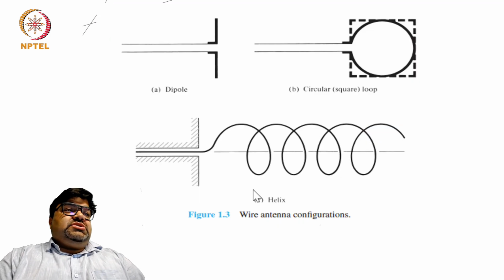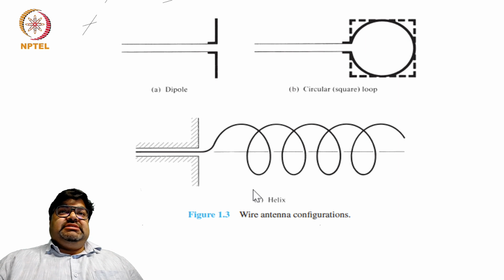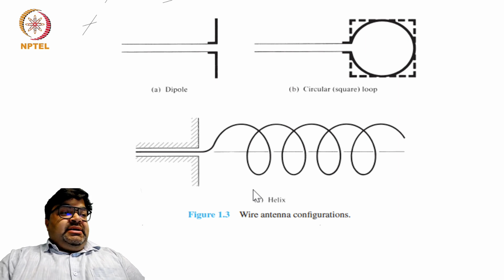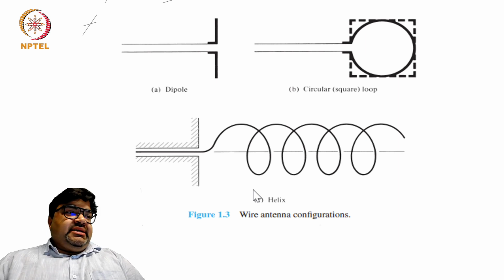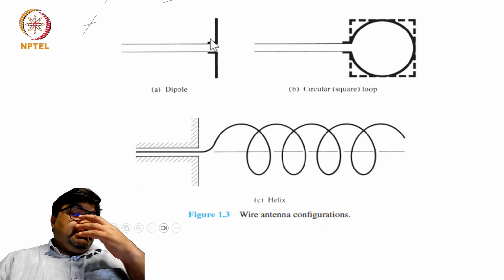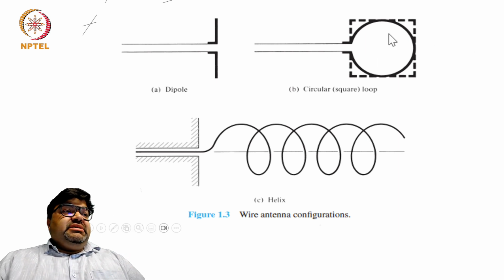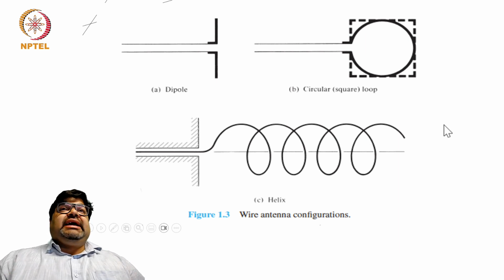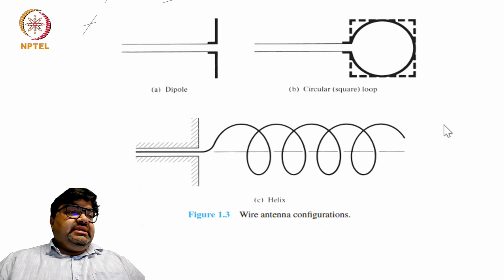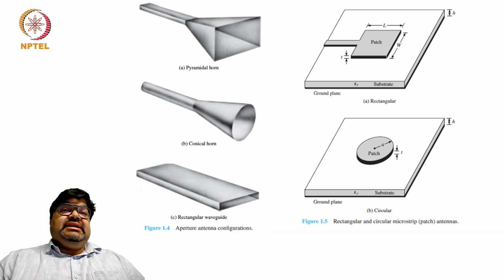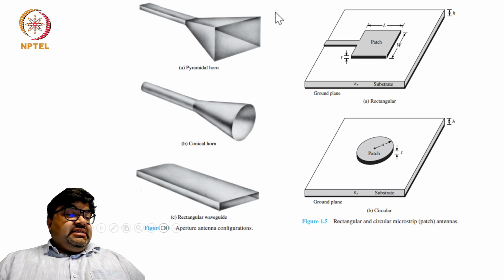Now, this big dish is massive, but at the end, what remains is that the receiving system starts with an antenna. A very basic antenna is the dipole antenna. You have the wires and you bend one 90 degrees, perpendicular to that. It forms a dipole antenna. Simple radials, monopoles, are also used. A simple circular loop antenna can also be used. A helical antenna can also be used. These are all categories of wire antennas. Okay. There can also be planar antennas, in different 3D geometry.